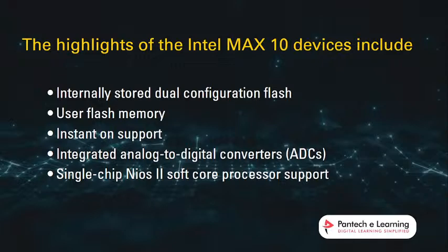And our MAX10 FPGA has an integrated analog to digital converter, so we don't have to write analog to digital converter code in a Verilog file. We can access the IO pins of the analog to digital converter. By using the pins, we can give analog input and get digital output. By using the pins only, we don't write Verilog code for the analog to digital converter.